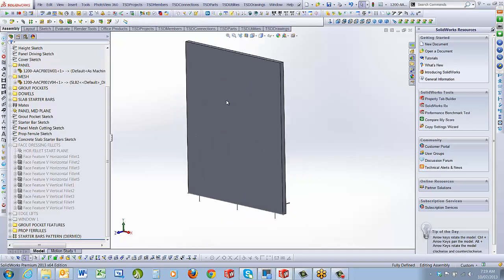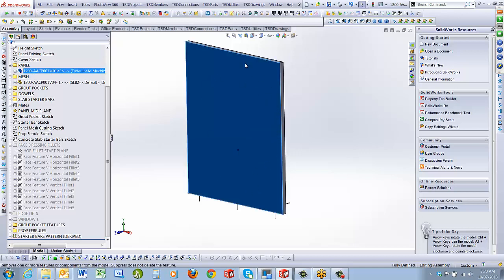So when you cut your panel or you do a groove in it, what we do is we just extrude right up to the very edge, and we might make the edge an offset so that the extrusion offsets from the edge, say 0.01, so it's really small. And what happens by doing that is that you'll maintain a consistent single face. Okay, so there is a little bit of a modelling tip there when it comes to doing your panels.